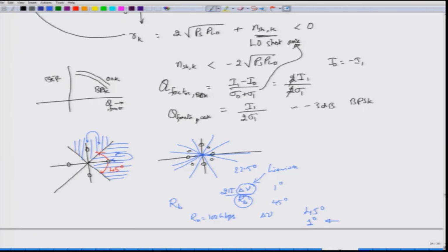Okay. So, the drawback for increasing the spectral efficiency of a single carrier system is that as you start packing in more and more points, okay, the allowable noise margin shrinks and the system specification also becomes tighter. Also, with the 1 degree variance that we want for the phase noise, the main drawback, apart from of course constructing the laser, will be how you are going to synchronize the transmitter and the receiver if the margin of error is just 1 degree, right.